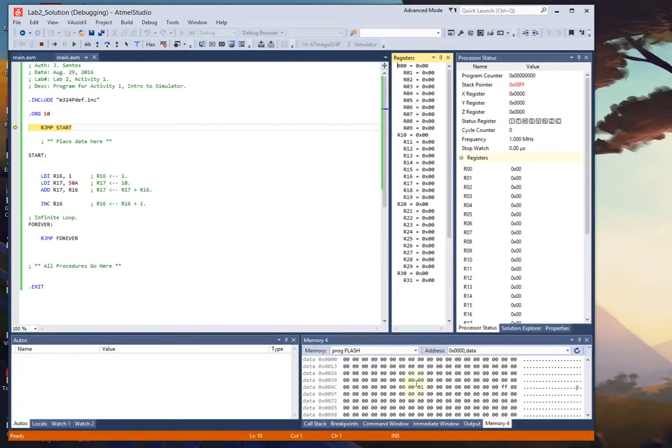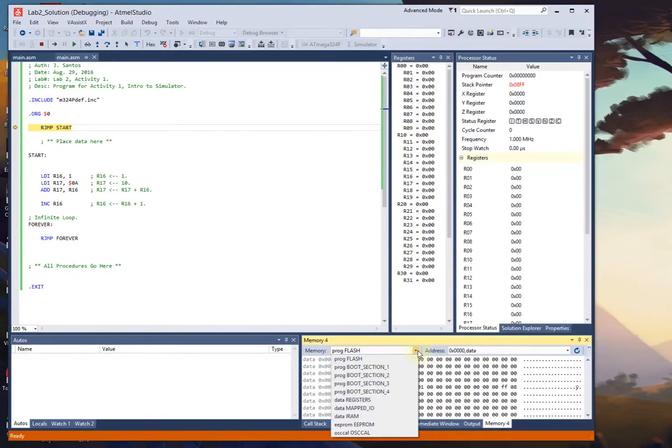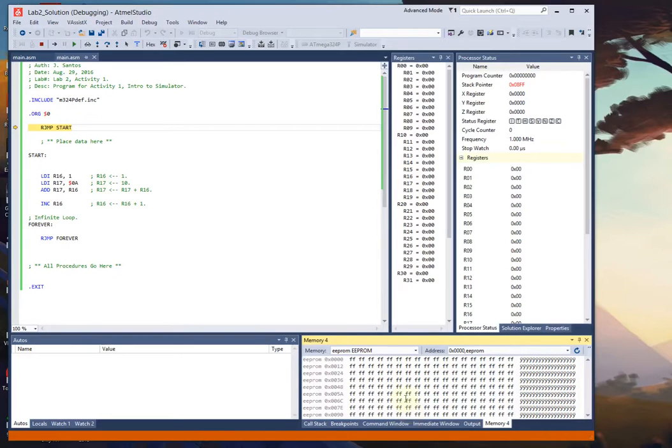All right. The AVR architecture has 3 memories. One is the flash, where your program code is stored. The other is data memory, which contains both registers. All of these registers are mapped into SRAM, or static RAM. And we can see I/O memory. All the I/O registers that control a variety of the peripherals in the device are also mapped to SRAM. And then EEPROM. In much later labs, we'll be working with EEPROM.